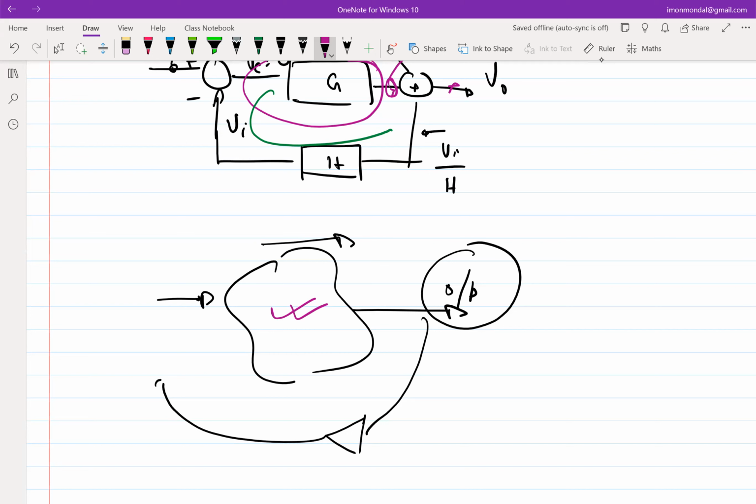But this intuition fails in a feedback network, because if the feedback network is working properly, if you increase the gain of this by a factor of 2, factor of 4, it doesn't matter. The output voltage will be set by the feedback block. Okay. So again, when you will be designing, keep this in mind, right?